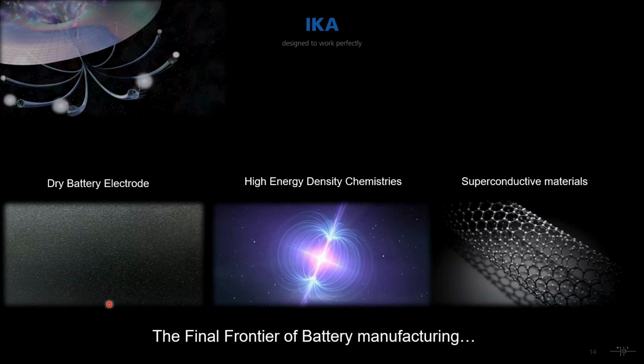And then, of course, from an environmental standpoint, you're not using that solvent, so you're not using any NMP or generating any wastewater. And additionally, you don't have the energy expenditure from large ovens that might need to be used to evaporate that solvent. So very interesting technology, very promising, but of course some challenges to handle there.